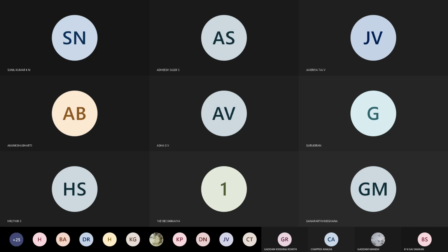Next we are going to find the output when only VB is supplied as an input voltage, and VA and VC are connected to ground. Now we find the output voltage with respect to VB alone. That is nothing but the output voltage VOB. And now these two voltages VA and VB will be reduced to 0, and only VC is applied. So through VC, the output voltage you are going to get will be considered as VOC.